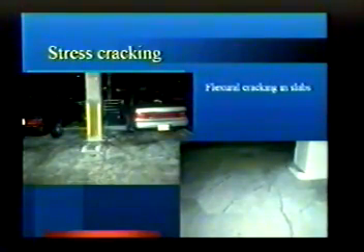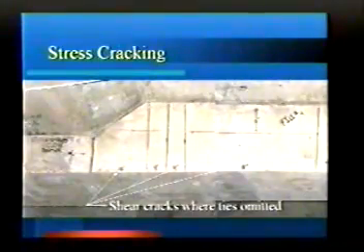Okay, the stress cracking. As I talked about earlier, this is actually a flexural crack. This was due to the rebar being in the wrong place. And here's a flexural crack coming through a repair. Now, why did that come through the repair? We had all this brand new nice concrete on it. Well, it's simple. Remember that moving crack? This garage floor moved. And as it moved, the cracks mirrored from the base concrete right back up into the patch. Okay, so again, you have to be thinking about your cracks. Are your cracks moving or non-moving? You may have to treat this differently.